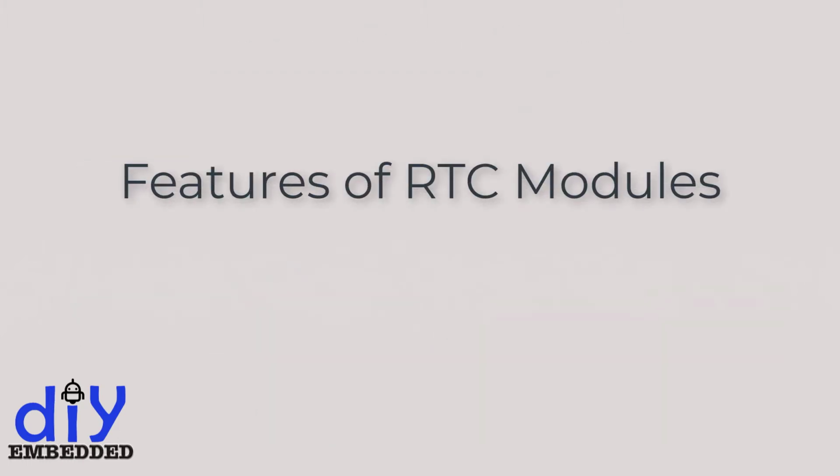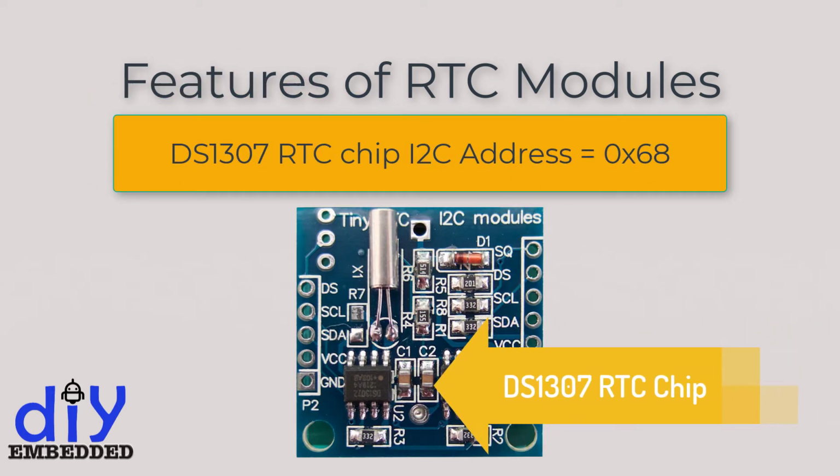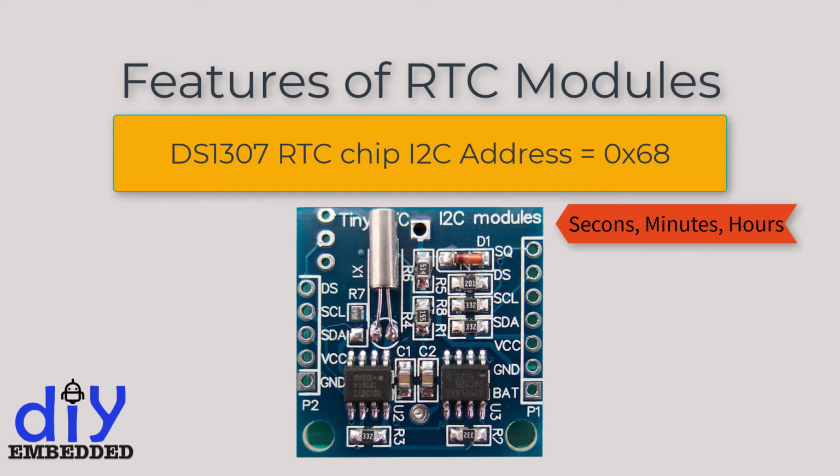So let's start with exploring different features of RTC module. At the heart of the module is a low-cost but quite accurate RTC chip from Maxim, DS1307. It is responsible for all timekeeping functions and features a simple 2-wire I2C interface, with which it can be easily interfaced with any microcontroller of your choice. The chip maintains seconds, minutes, hours, day, date, month, and year information.